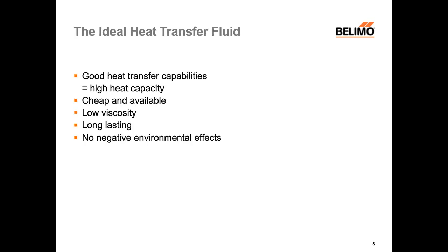So, the ideal heat transfer fluid has, of course, good heat transfer capabilities. That means a high heat capacity. It is cheap and available. It has a low viscosity. It is long-lasting, and it has no negative environmental effects. Anyone have an idea what this could be? Yeah, sure. It's water.